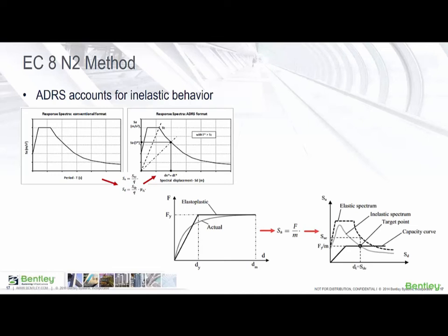Similarly, the idealized force displacement curve is also converted to ADRS format using the transformation shown above. The intersection of the capacity curve and inelastic spectrum designates the performance point where the displacement capacity equals the displacement demand.